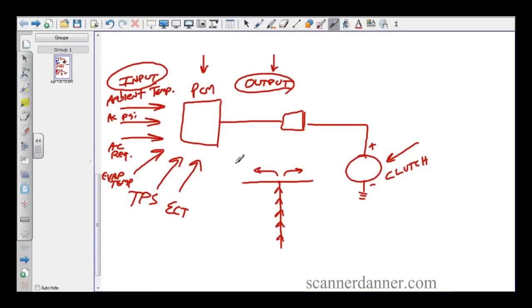So I'm right here, and the test that I am going to do right here is my scan tool bidirectional, okay? And if I command this, and where's the scan tool at? It's right here. We're interfaced with the computer. My scanner's down here. And what I'm going to do is tell the computer, hey, turn that AC clutch on. When it does, it should.